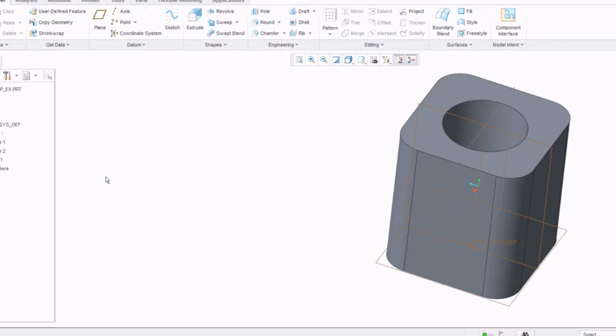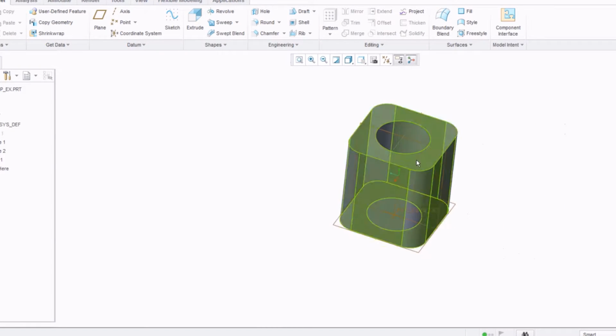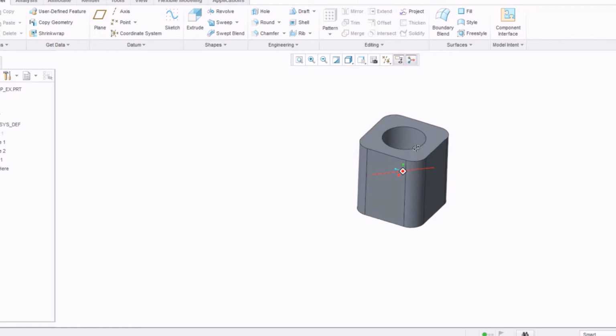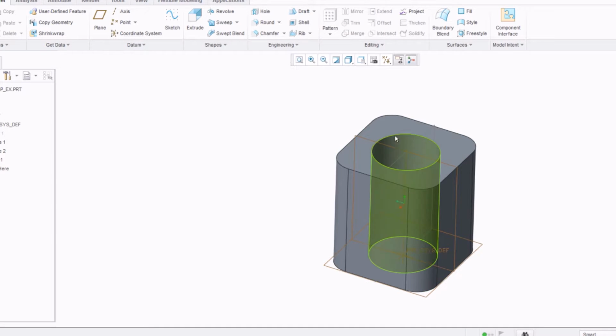Okay, we'll go ahead and show you the chamfer feature now. Chamfer is pretty important in design on lead-ins. So if you can imagine, maybe this is a block with a threaded hole in it, and I have a screw going in through the top. Trying to put that screw in with these sharp corners, there's a high probability that it would get caught on one, it would go in at an angle and become jammed. The easiest way to get past this is to add a small chamfer. It's called a lead-in chamfer.